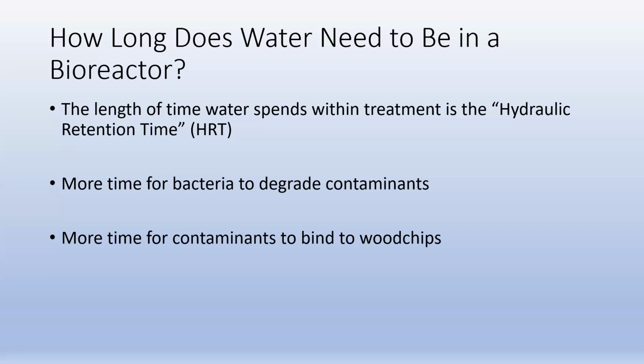Now that begs the question, how long does water need to be in a bioreactor? Well, the term for the length of time that water is going to spend within a treatment system is the hydraulic retention time, or simplified, the HRT. What this basically comes down to is how long or how short you let that water sit in these bioreactors.